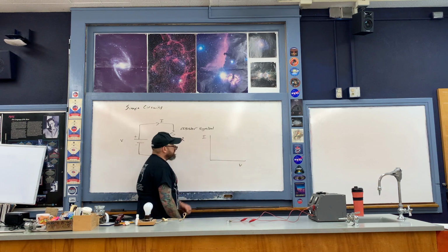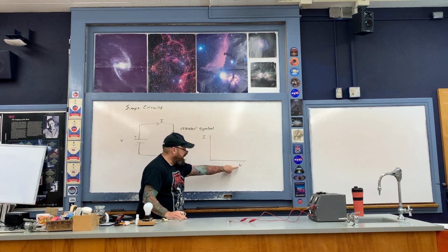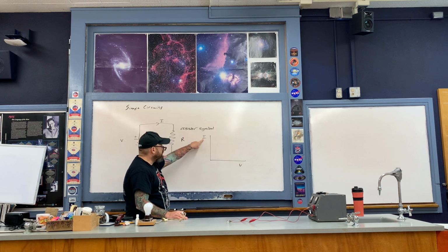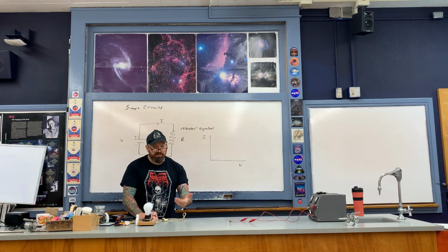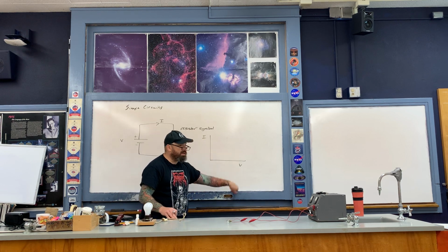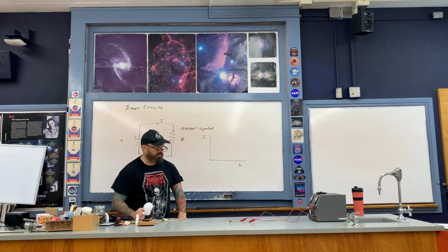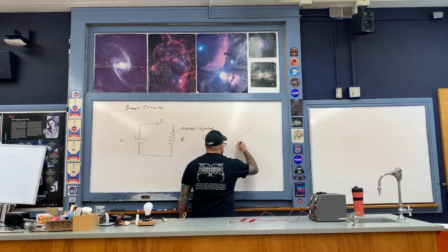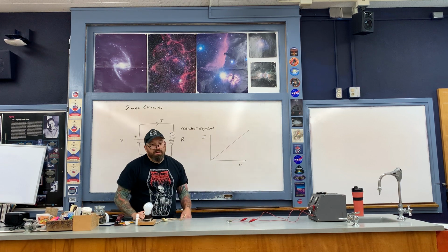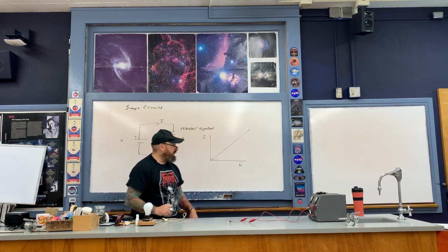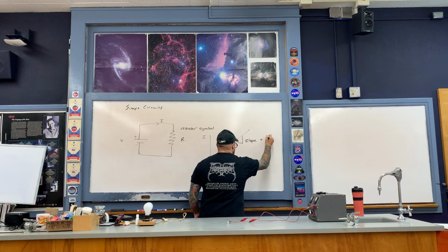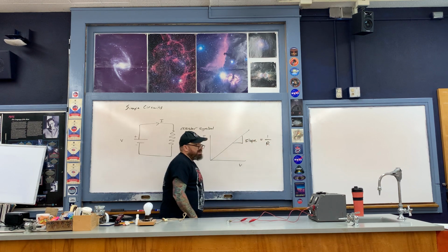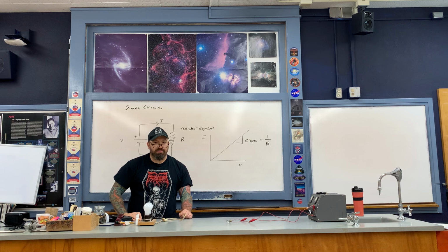Like so. So in other words, the current itself is a function of the voltage V. So this is the independent variable, and the current, of course, depends upon the steepness of your hill. For most metals, the relationship between the two quantities on this graph is linear. Like so. Okay, now the slope of the line here has meaning. The slope of the line is equal to the inverse of the resistance R.